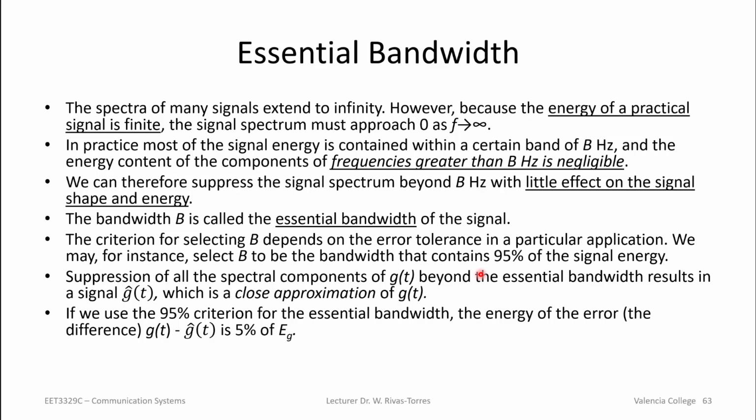Now, we normally don't deal with infinity quite well, and for all practical purposes, when we're talking about signals, there's a point where, after a certain frequency, the energy that's contributed is fairly small, or we could call it negligible, right? So what we would like to do is find that bandwidth after which the signal has negligible energy, and we'll call that our essential bandwidth, right?